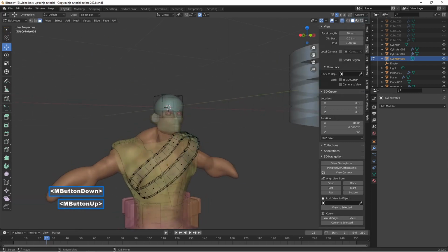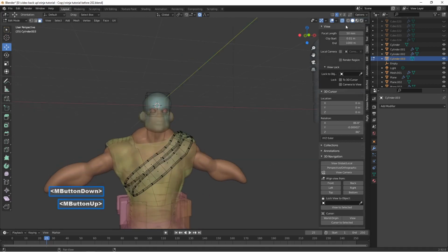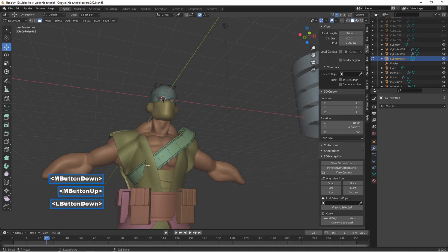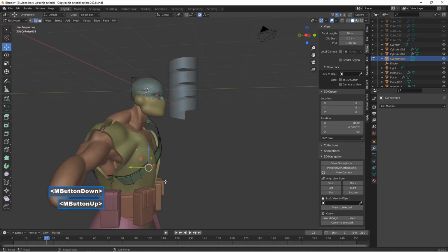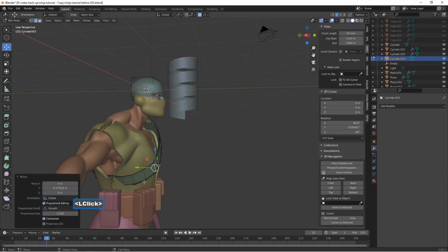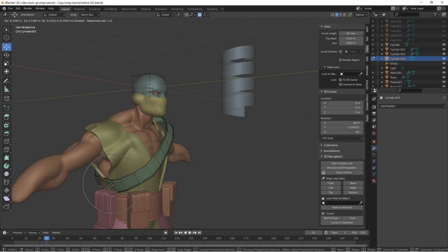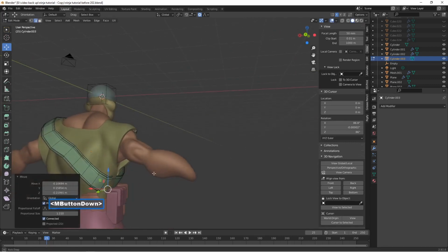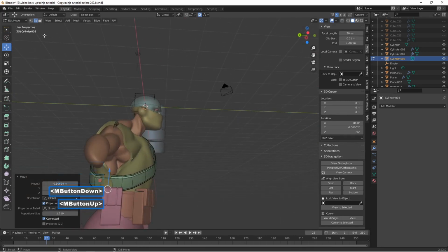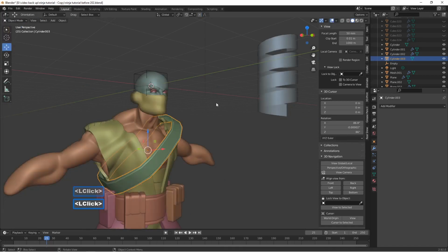The shoulder, you want to be careful, particularly with these edges, you don't want to really have them change much. So here, we can select here, press G and then Z. And this should let us adjust the belt without making it not look right. So this is something that's done better in edit mode than in sculpt mode. So we'll press G and then move that, left click to deselect, go to the upper left and go to object mode.